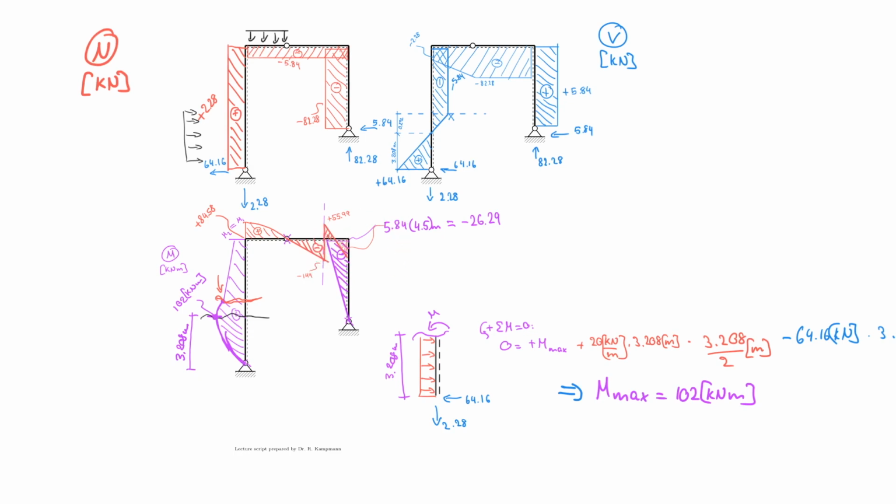So with that said, I think we now understand how to calculate frames that have right corners and a hinge, right? The hinge was the starting point that challenged us, because we had to understand that we can solve the support reactions in a very specific way.